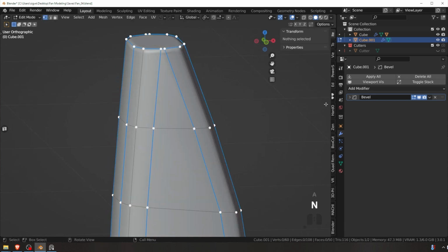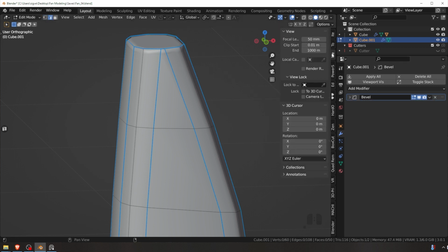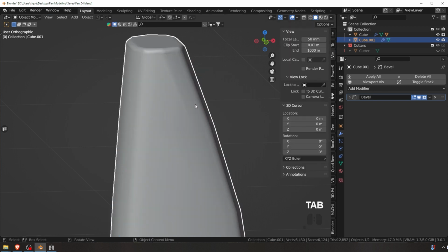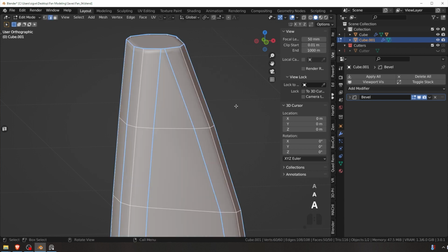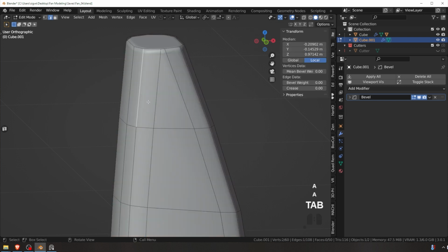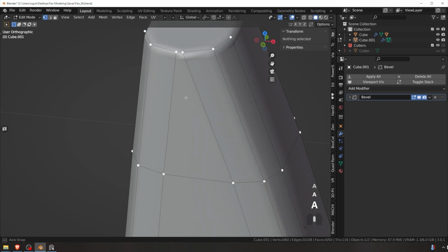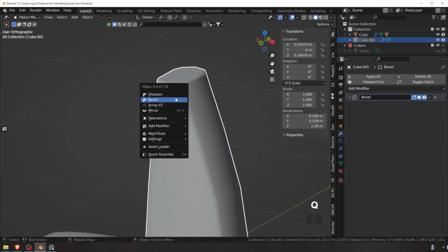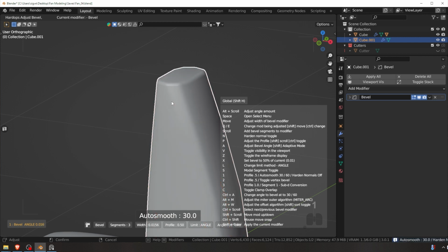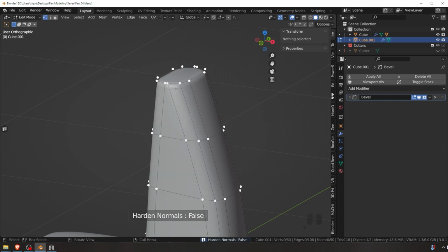So first I can already see that I'm running bevel and it's at an angle. And let's see, maybe we have some weighted edges. Mean bevel weight, yep, but that's not messing this up. Let's just go into this bevel menu and hit 1 just in case. So everything resets, 1 and then N to recalculate normals. That often helps us.